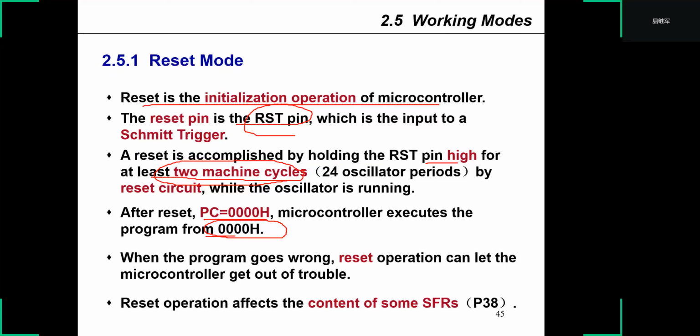Reset operation affects the content of some SFRs. After reset, most of the SFRs become 0, but the stack pointer becomes 07H.